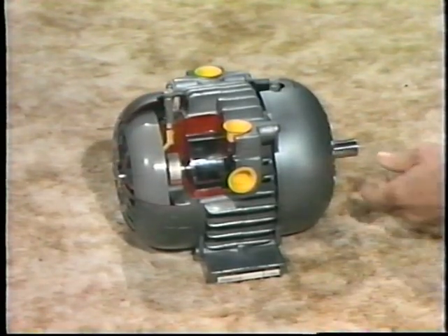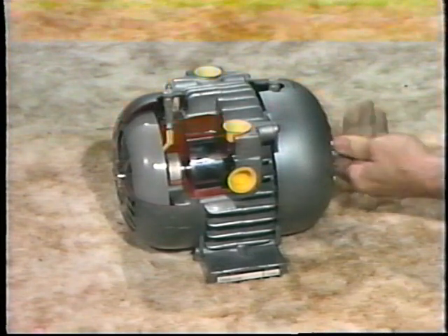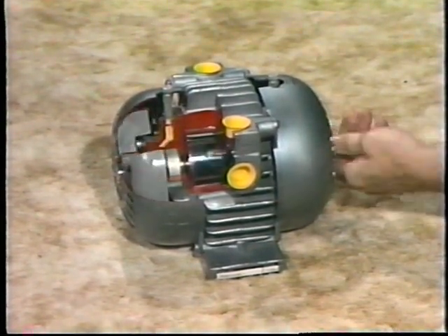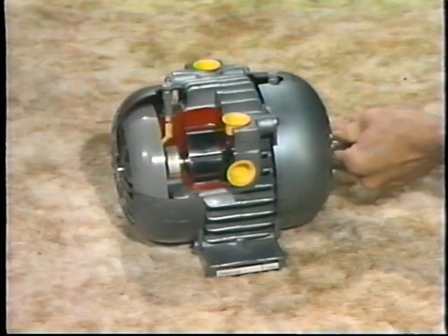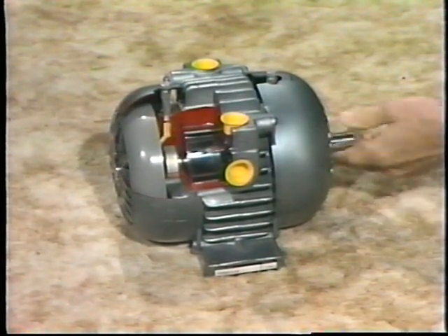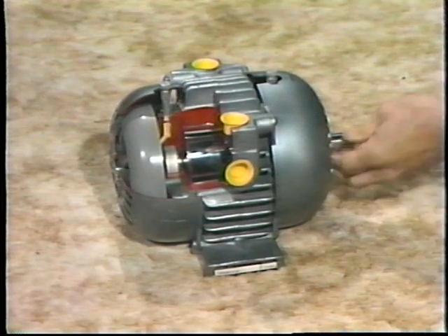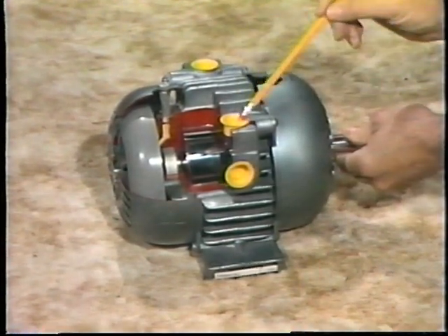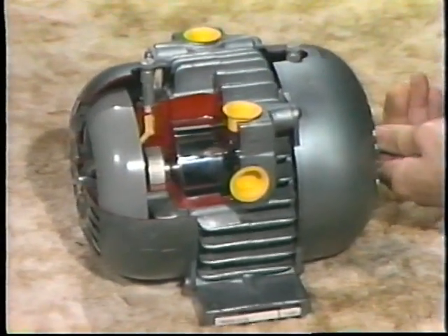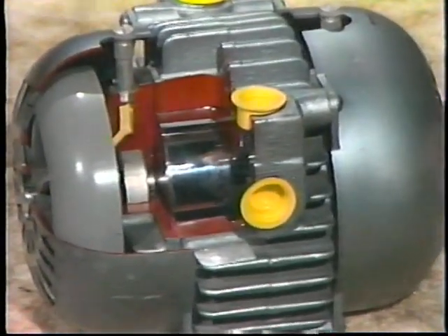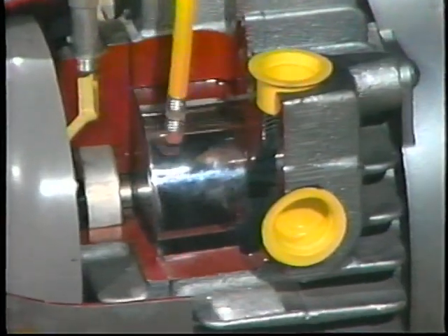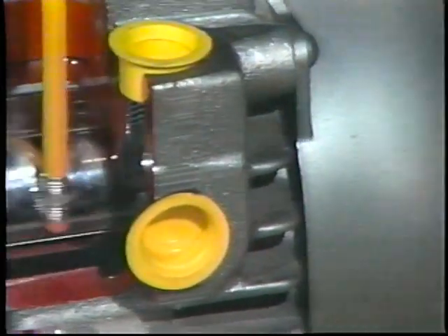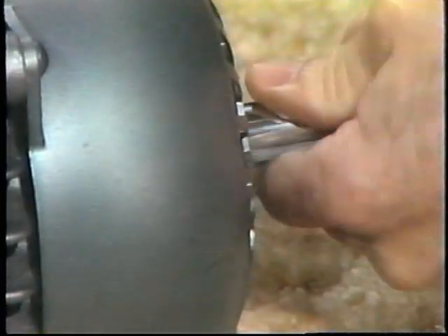The vane compressor you see here is a positive displacement compressor. It's a rotary type, and it can develop a relatively smooth flow of pressurized air. This is the drive shaft, and here are the inlet and outlet ports. Inside the housing is a rotor, which supports these floating vanes. The rotor is connected to a prime mover by means of this shaft.